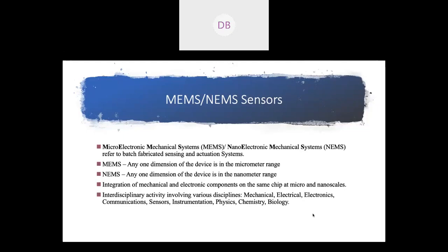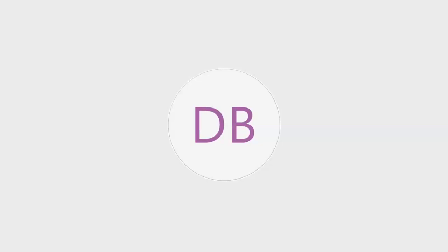That is where the actual complication arises, and that's why even though the cost of the semiconductor circuits has been going down, the cost of the MEMS sensors is not able to be brought down because of the complexity in the fabrication process. We cannot have a standard process for every device, or for every sensor. So obviously that is where the major difference arises.